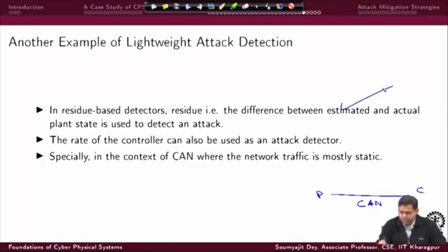In our previous system, we had the controller and also a detector, and whenever your measurement came, you fired up the detector, calculated an expected measurement value, compared it with the measurement you are getting, and if that estimation error is higher than the threshold, based on chi-square statistics or a norm based detector, whatever you are using, you say there has been an attack or not.